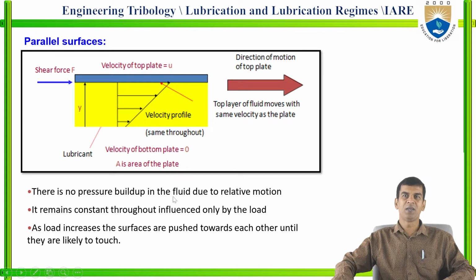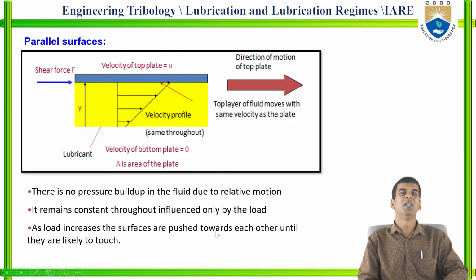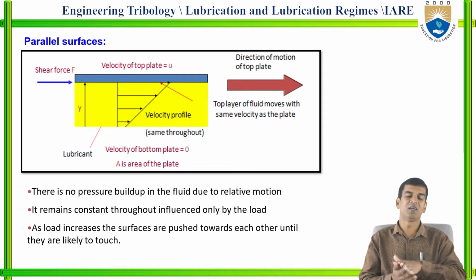There is no pressure buildup in the fluid due to the relative motion. When the two surfaces are moving relative to each other in this way, no pressure buildup takes place. Pressure remains constant throughout, influenced only by the load. As the load increases, the surfaces are pushed towards each other until they are likely to touch each other.